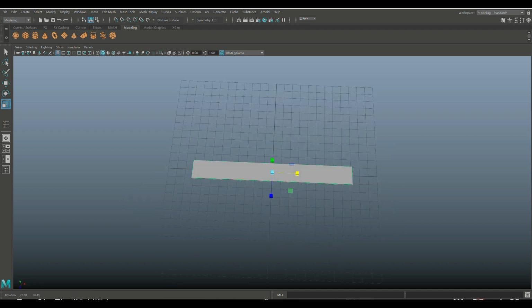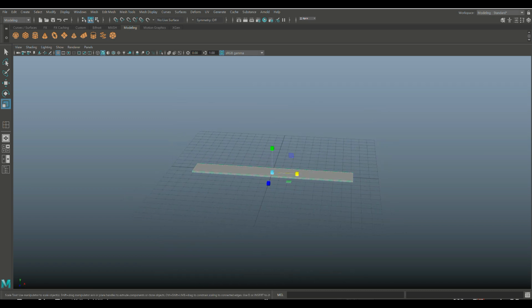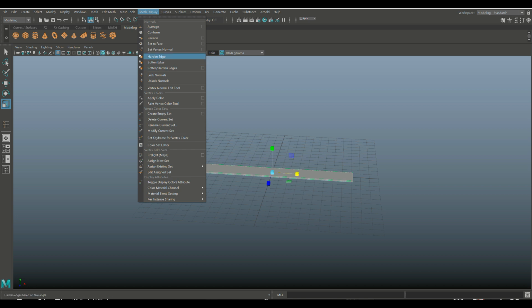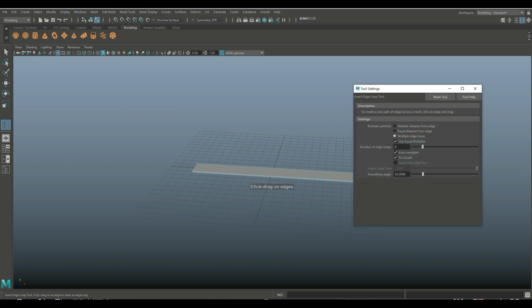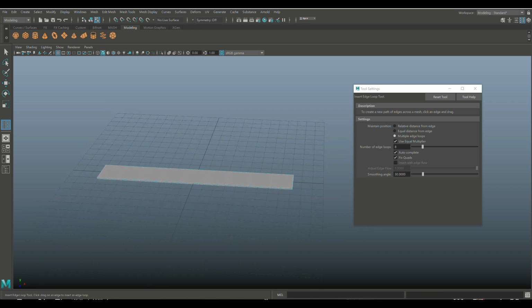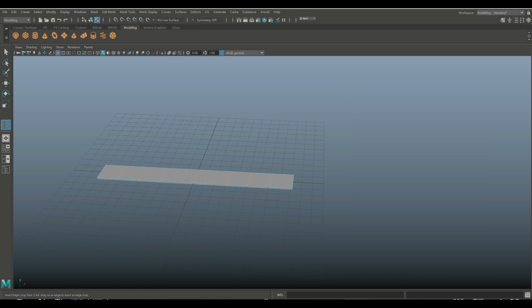Now in order for us to bend this properly, we need some subdivision, right? So we're going to go in here, we're going to go to Tubes, into Edge Loop, option box, we'll set to 8 since that's the last I used, which is okay. So that should work. And then I'm actually going to set this to multiple and 1, and I'll explain that in a sec. By doing that, whenever I click in a section, it will make one exactly in the middle.